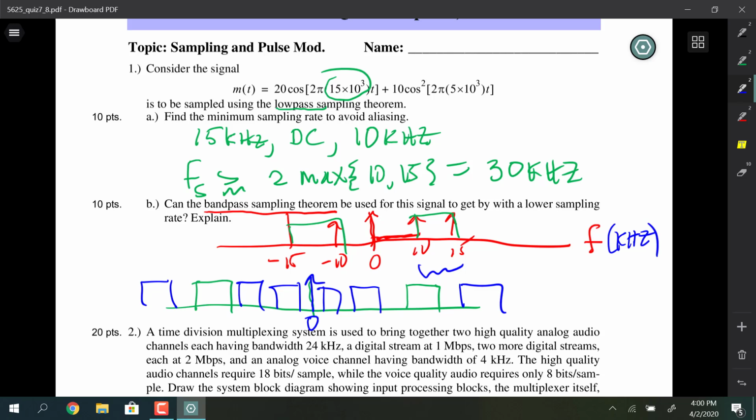But generally, when you do bandpass sampling, you do something else, and that is you will put a bandpass filter around the signal from the get-go to make sure nothing else ingresses and starts creating mixing products, because that's what the theorem has to assume, that you've got a limited bandwidth that you want to undersample.